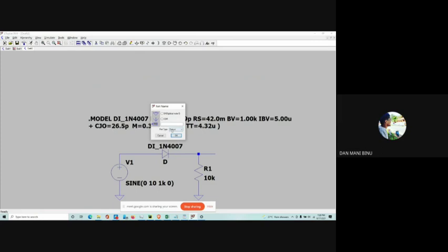Where is that port type? Where did you select that box from? That's the label, right, like yesterday. You can select it from this label net. In that window it will be automatically set to none. You can use none, no problem at all. But if it's an output, it's just an extra thing, you can use it or not. If I change it to output and enter a name, let me enter Vout and click on it, I will get a label like this, and I can paste it here.